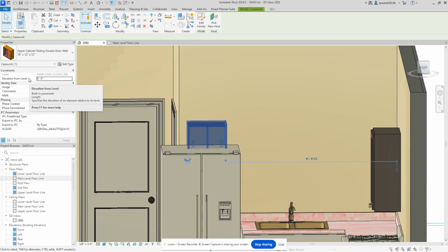If you're getting custom cabinets, they're sized to the nearest 16th of an inch. So when we give out sizes to order cabinets, it's always by inches to the nearest 16th of an inch. And that's their width, the depth, and their height. We never call them out like 2-foot cabinet or 3-foot cabinet. Always by inches.